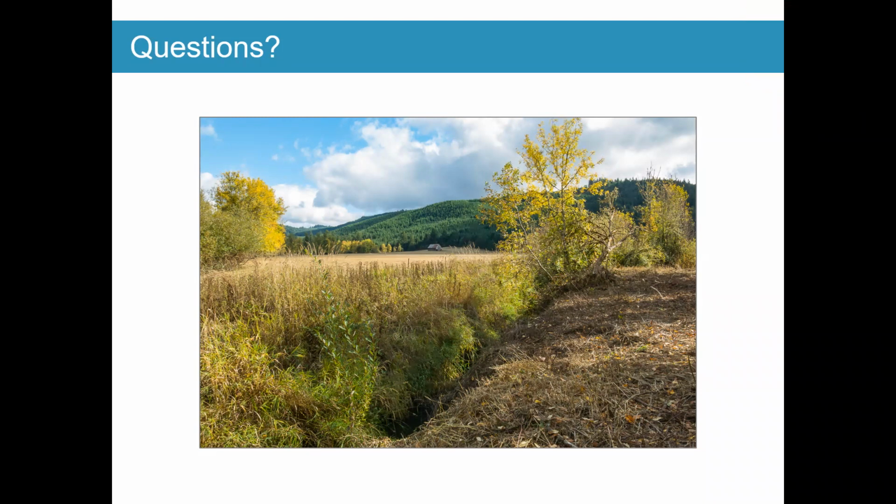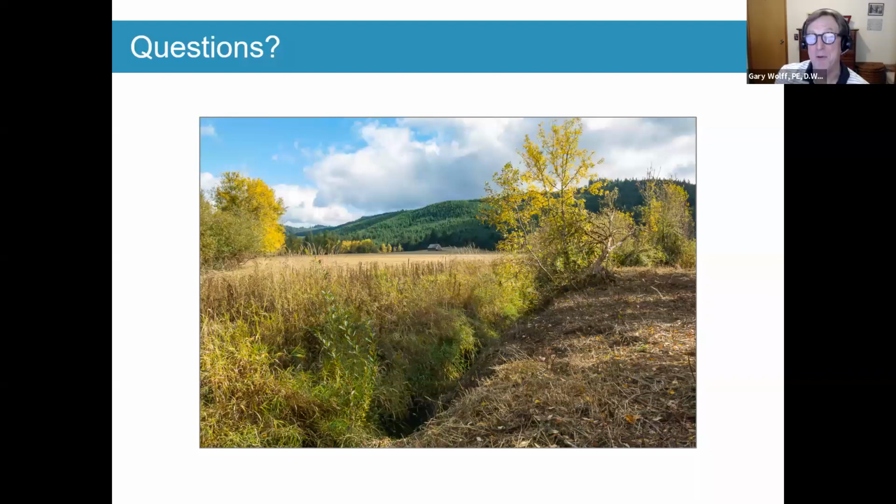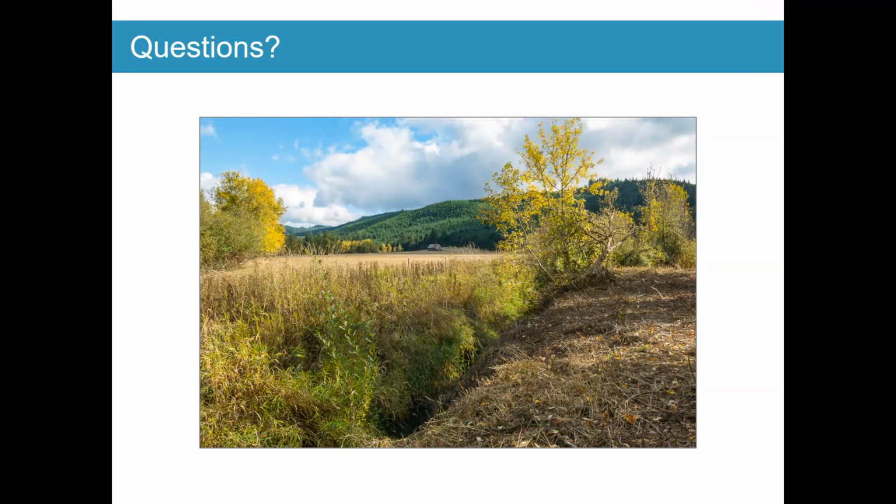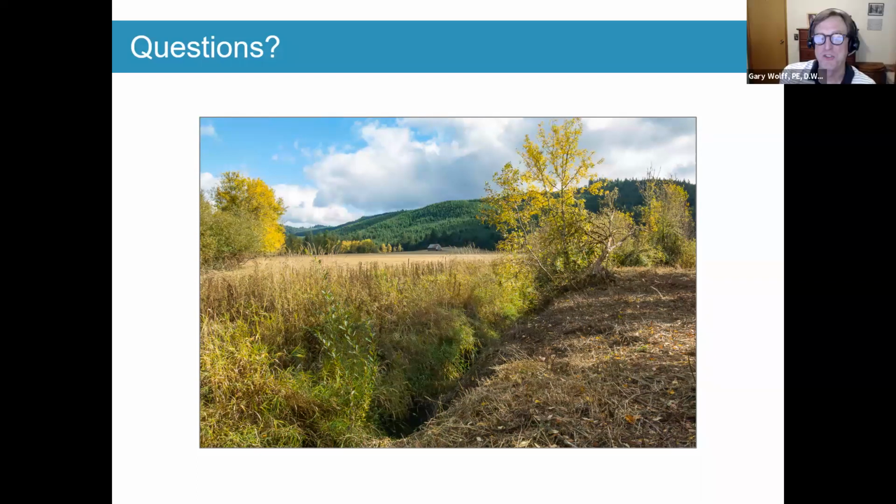But go ahead, Gregory. I'm intrigued by the fact that I'm up in Portland and we have lots of flood regulation, and I'm intrigued by the completely different world down there in terms of requirements. Well, this was an approximate zone A. So there is no strict no rise, and I don't even think that would be true in Portland, because it's not a floodway. We're in a very rural setting here, so the floodplain regulations, by the fact that there's no floodway, are probably a little more relaxed. But we essentially met a no rise on this project. If we ran a one-dimensional model, I think you would see that.